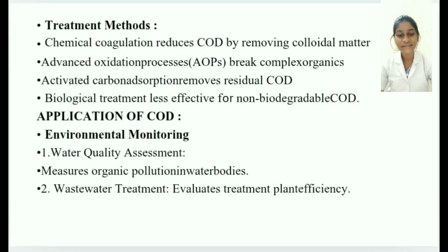What are the methods involved in COD treatment? Chemical coagulation reduces COD by removing colloidal matter. Then advanced oxidation processes break down complex organics. Activated carbon adsorption removes residual COD. Biological treatment is less effective for non-biodegradable COD.